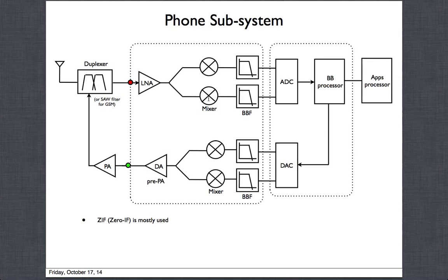See, the flicker noise is very high around DC. If you see most of the standards now, they are multi-carrier systems. When they are multi-carrier, the power is actually distributed among multiple carriers all over the frequencies. So it's not just a single carrier, a single sine wave at DC or close to DC carrying the information.